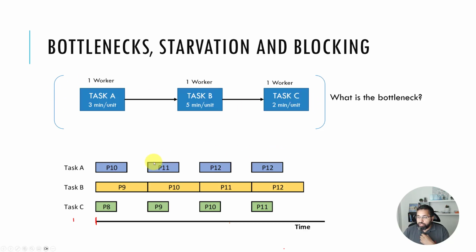Okay, so this blocking and starvation is what leads us to the most important idea in this lecture, which is that the entire capacity of this process is determined by the capacity of the bottleneck.